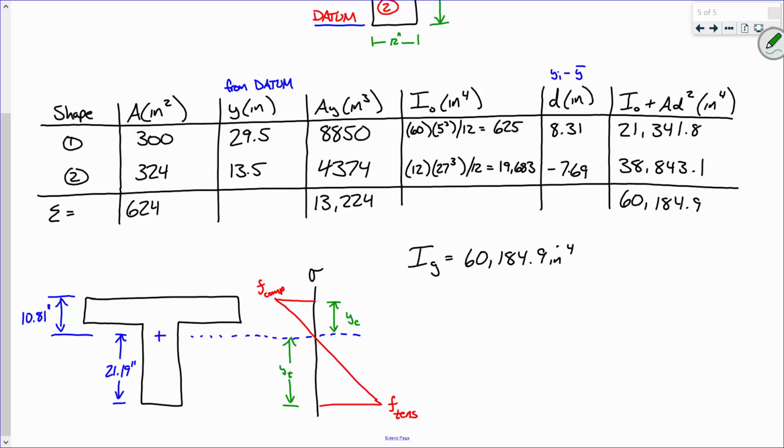So this is sort of one of the ribs of those beams in the parking garage picture that I showed you, remember? So that's going to be those ribs sticking out. They're going to be seeing primarily tension. That flat portion on the top, the slab, is going to be primarily seeing compression. Does that make sense?